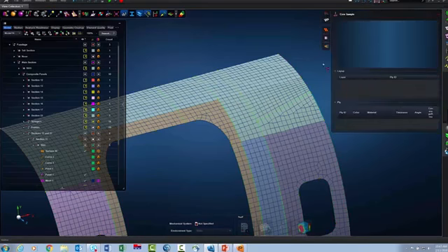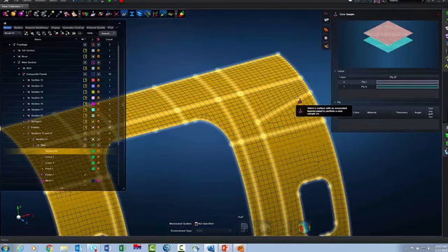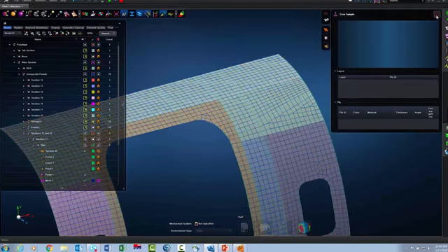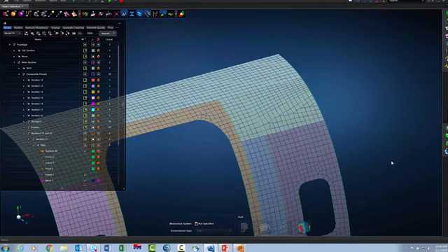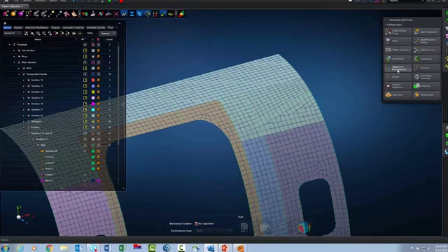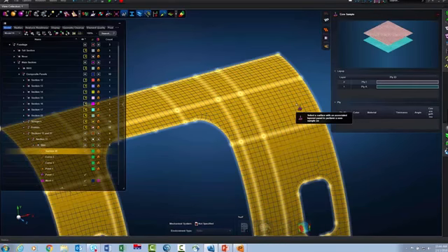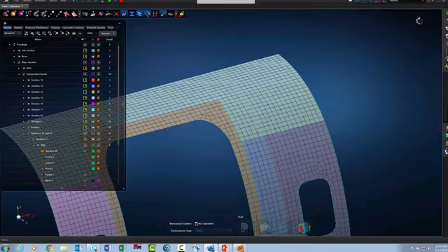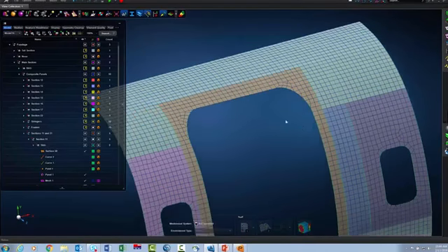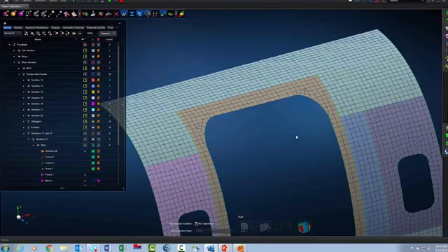And let's go back to the core sample tool, and what I see here is I still have that zone, I still have those two layers. So I made a change to the model, to the mesh, I actually changed the geometry, I split a surface, and Apex is managing the zones and the layup for me. I can even come in and suppress that curve that I just created, so we'll suppress it so the mesher doesn't see it anymore. We'll go back to the core sample tool, we still have two plies. Once again, Apex is managing my zones, managing offsets, all that information automatically for me, okay? So that was a mesh-based or geometry change that was dictated by the mesh.